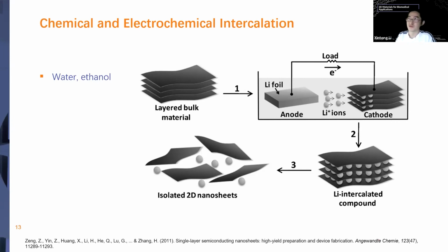Yeah, that's a super good question. The 1T phase is a metastable phase for MoS2, but it can also be pretty stable compared with other TMD materials. In my research, I never had this problem because I used CVD MoS2 monolayers grown by the company or other groups, which is definitely the 2H phase, or mechanical exfoliation, which is from a 2H bulk material. So the result is definitely a 2H one.